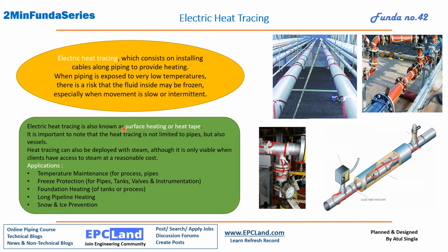Now electric heat tracing is also known as surface heating or heat tape. It is important to note that heat tracing is not limited to pipes but vessels also. Okay, we go for heat tracing of vessels also. Now heat tracing by electric or steam is purely the client's choice. If steam is available at a very reasonable cost, then the client goes for steam tracing. Otherwise we can go for electric tracing also.